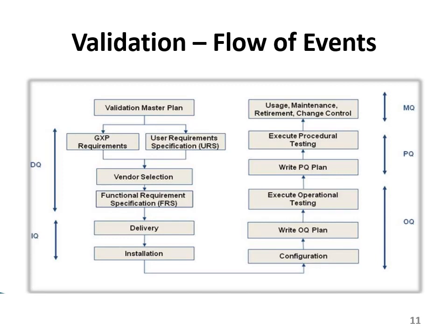Execute operational testing. Now you have written the operational qualification plan, and now test it: is it working? If it is working, excellent. If it's not working, you need some changes, do the changes. Then the performance qualification, PQ: write the PQ plan, how to perform on the machine. Execute procedural testing, then again test it.